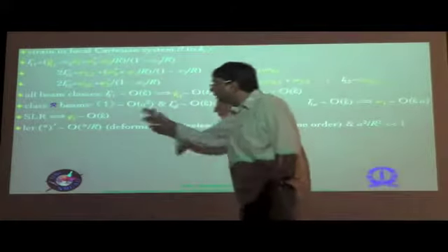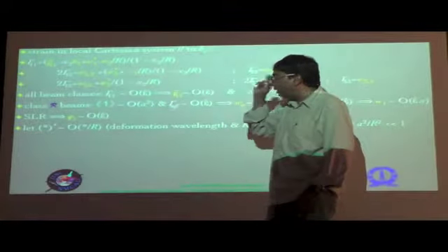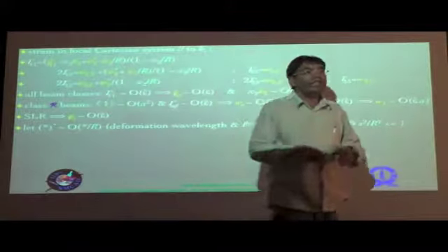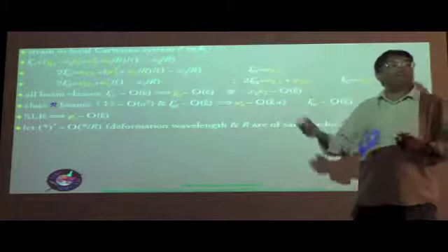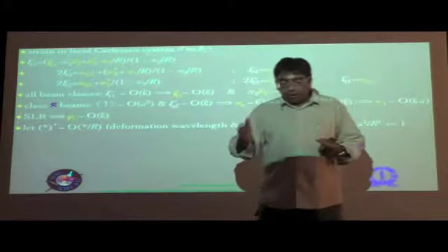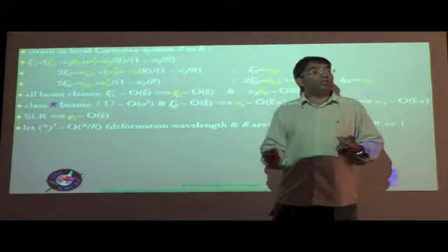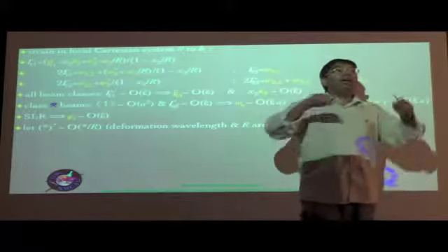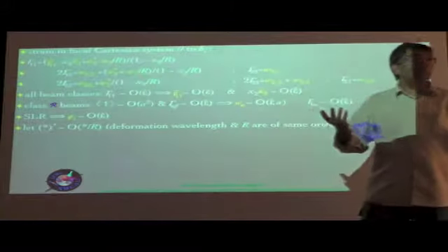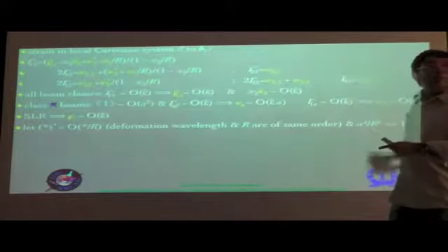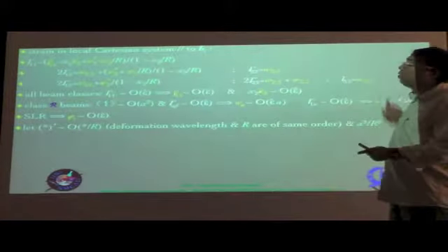Next, there is a slightly dicey thing over here in terms of how you handle the initial curvature. The initial curvature is in terms of the initial radius of curvature, big R, so we have more than one geometric parameter to deal with. We take the situation where this big R and the L are of the same order of magnitude, which is indeed the case if you look at the undeformed configuration, where you had a quarter circle, or